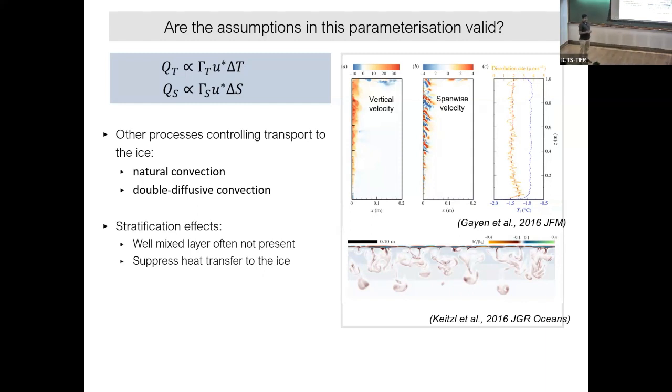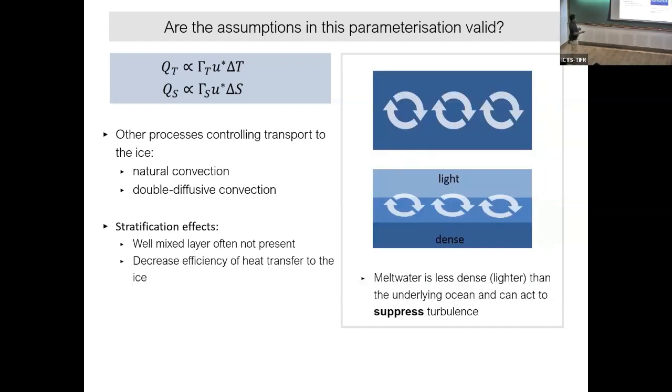Okay. So in natural convection, we also try to calculate the drag coefficient, but that has no meaning. Okay, the transfer coefficient has no meaning because the functional relation doesn't exist, because the functional relation does not depend on the U, it depends on the temperature difference or salinity difference across the boundary layer. Now, I already talked about this. Similarly for salt, they use the same functional relation, called heat transport and salt transport. These are again called bulk formulas.